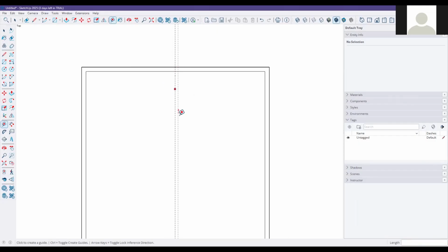For example, once you're done with this wall, you're going to have one bedroom here, right? I want to say this bedroom is 10 feet by 8 feet. So again, I have to type T on the keyboard and then drag this line in 8 feet and hit enter.